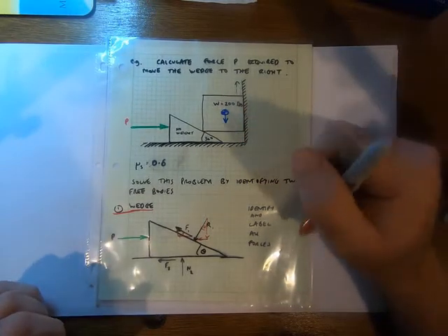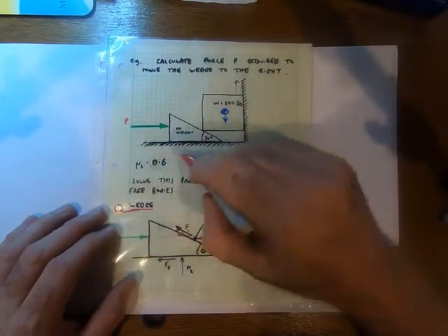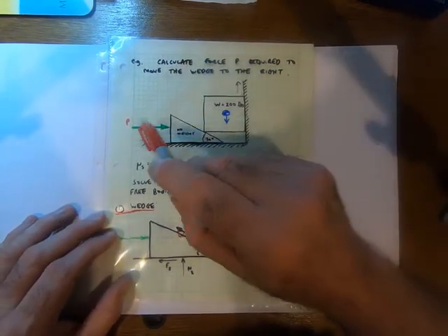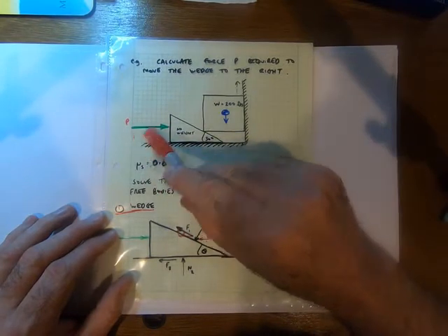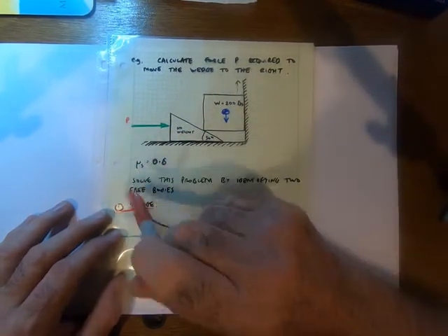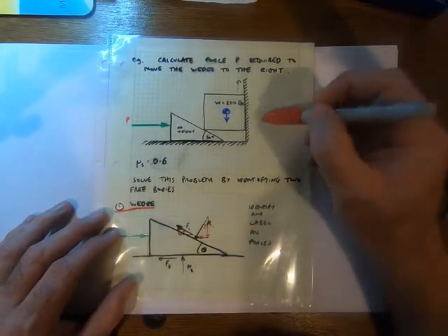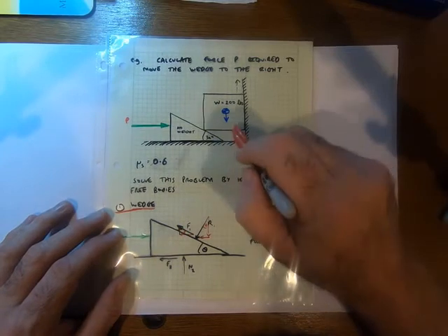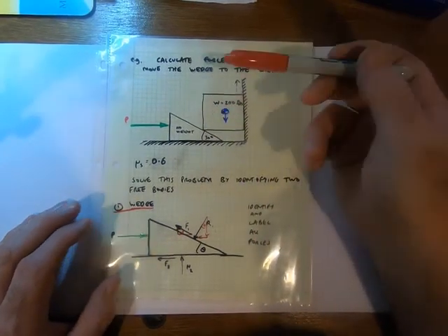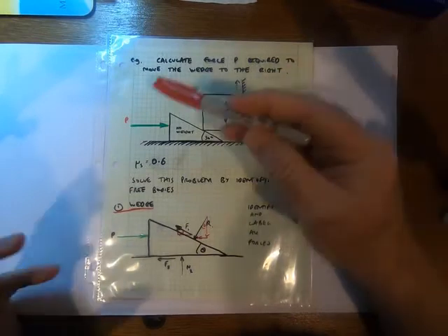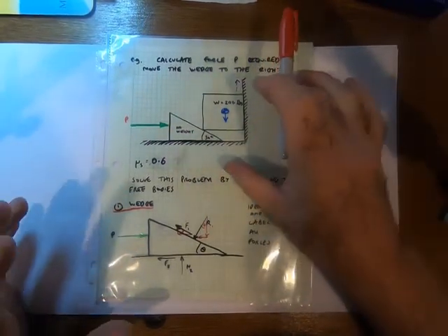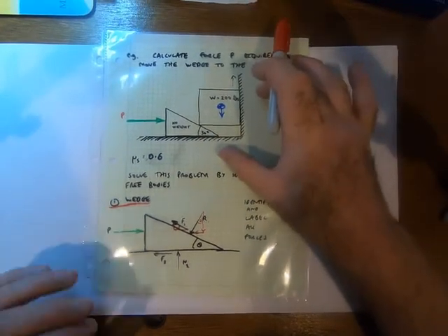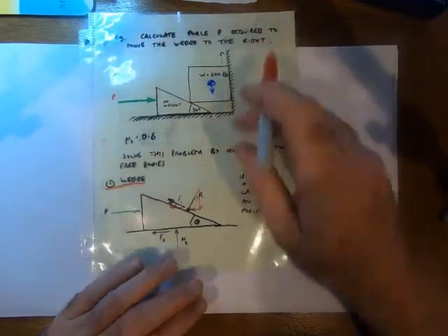Make sure that you are consistent with your directions and your signs. For all of my subjects, I always state: draw the sketch, show the forces, and then use this, because it actually defines what the variables are. So W here I know is going to be the weight, P is the restraining force. I don't have to write that down somewhere, it's defined in the sketch. And then the direction of these forces is also shown, and that direction transfers into my equations, whether it's plus or minus. So the sketch is very, very important: it defines what the symbols and the forces are, and it defines their orientation.